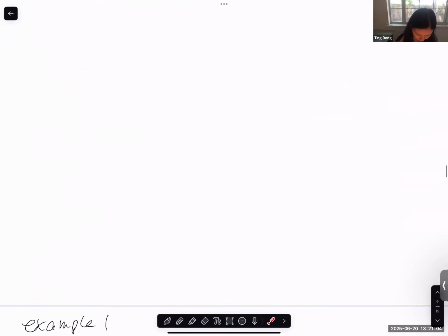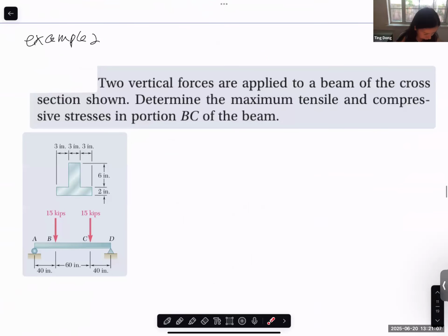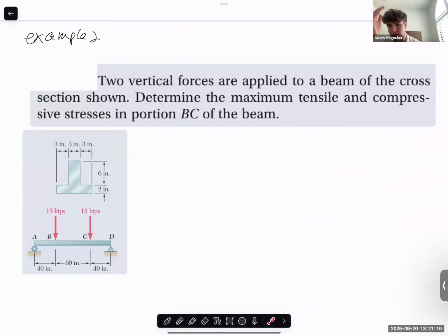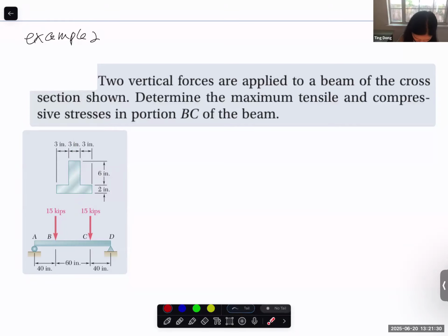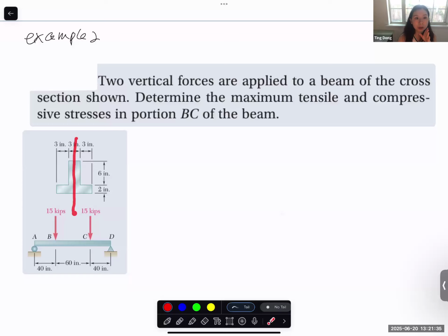Let me show you how to find the centroid of this one using this example. I have a question. If we already know the y is guaranteed to be where the centroid lies, why are we finding the centroid for the y and not the x? Like you said, the midline is where the centroid is for sure going to be, and we're finding the horizontal direction. Wouldn't that be the x? I may have said something wrong. You definitely know that the centroid should be on this line, right? Now you just need to figure out the y direction. Okay, thank you.